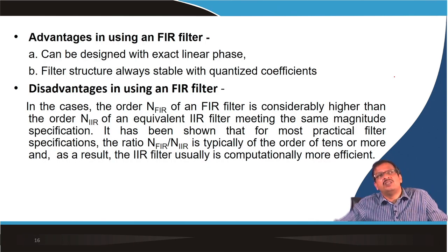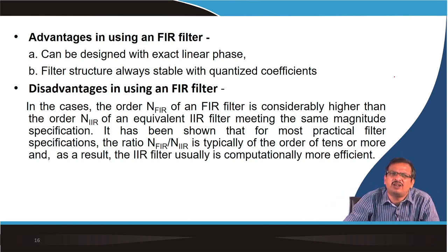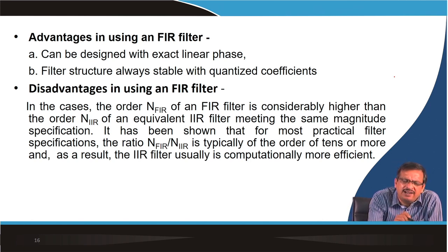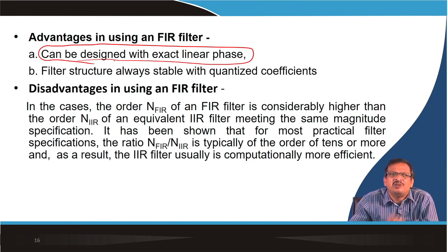Now I come to the advantage. Why most of the time are we talking about the FIR filter? Many times we are not talking about the IIR filter implementation. In digital filters, mostly we are talking about the FIR filter. Why? The advantage is that it can be designed with exact linear phase.